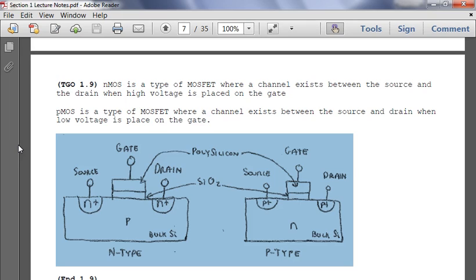I'm describing this a little down here already for some of you. But when you put in a 0, it's going to go to the P-type and N-type. The N-type is going to keep pulling these up so there will be no channel. Here, it'll push them down, it'll create a channel, it'll come from the supply voltage, and you have a 1 on the output. So that's how you create the inversion.